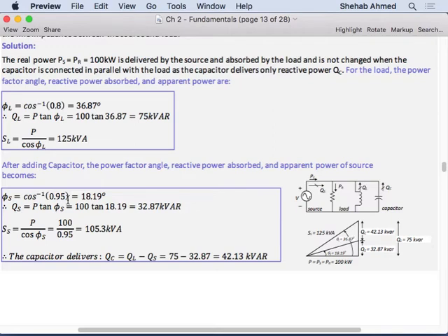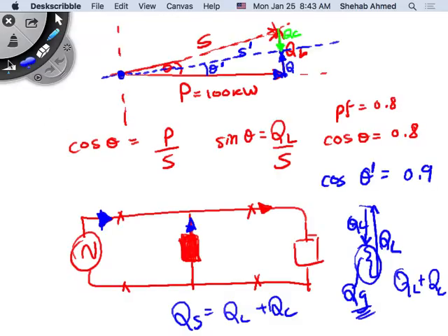Yes? Do we have variable capacitors in the market? But that's power electronics based. No, as a physical thing, the capacitor itself varying, I don't think so. Typically what we do is you have a fixed capacitor and you add power electronics to connect it intermittently to the power system. The technical term for that is static VAR compensator. Static refers to power electronics, basically. It's called SVC, static VAR compensator. VAR is volt ampere reactive, right? It's compensating the VAR in the system.